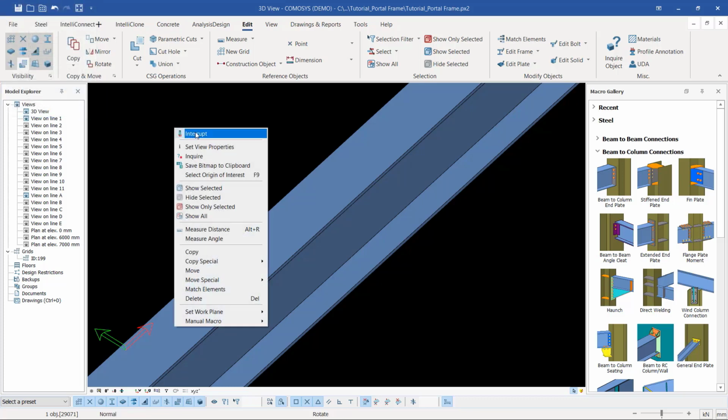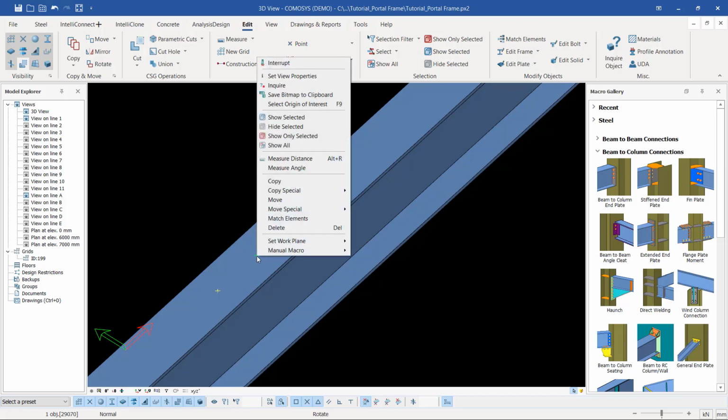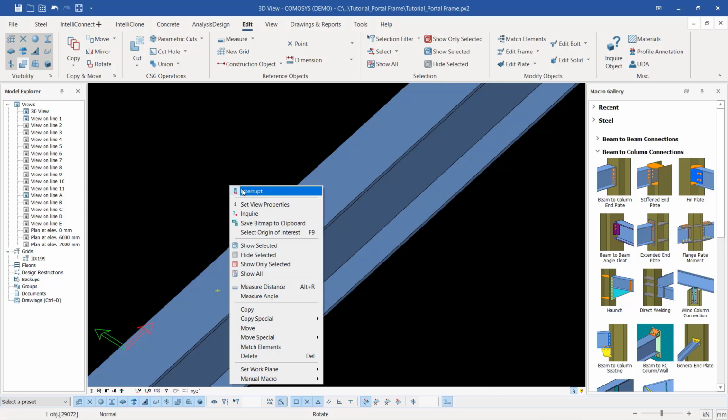So once that has been done, it has been given an offset against the x-axis. Now I want to add another point, and I want to add another offset. So instead of repeating the same thing, just copy the midpoint, the initial midpoint, then pick it from this particular point and place it here. So we have a point right there.